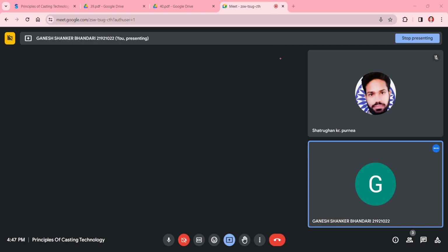So that will create the erosion scab on the casting. In this case you get a casting like this, and in the other case you will get some extra solidification on your casting. So that is going to be the answer. Erosion scab may occur where metal has been agitated or has partially eroded the sand. Cold shut we had already talked about, and hot tear we also talked about. So the answer is erosion scab.